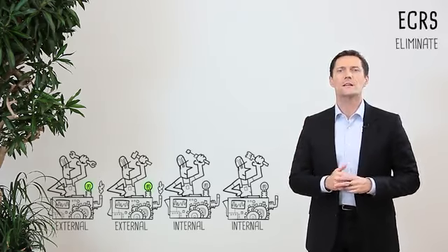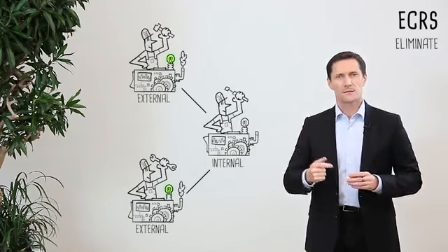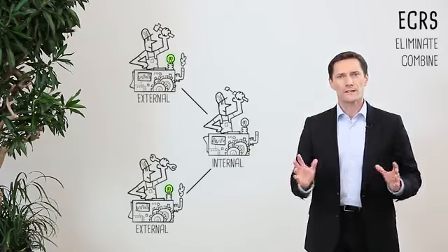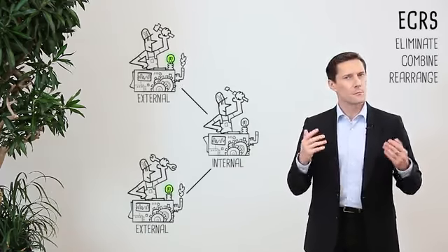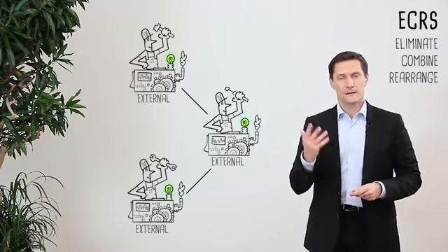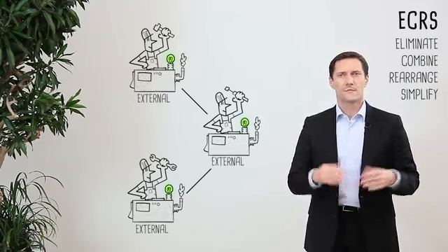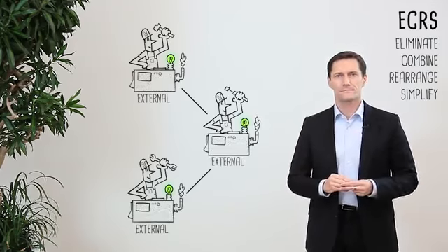The optimization of the process follows the ECRS logic. E means eliminate. Eliminate useless process steps. C means combine. Run steps in parallel. R means rearrange. Make internal steps into external ones, as I said before. And S, simplify. Simplify the work by using tools or modified equipment. SMED in total is very useful in companies with diversified products that require frequent machine resetting.